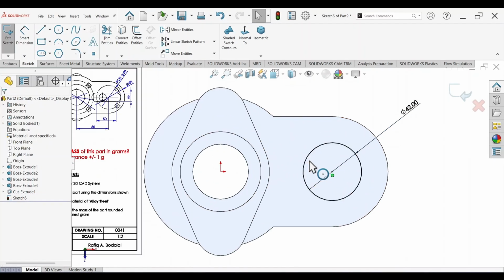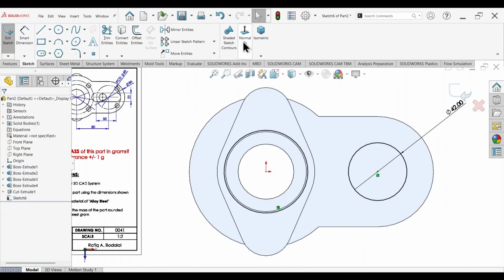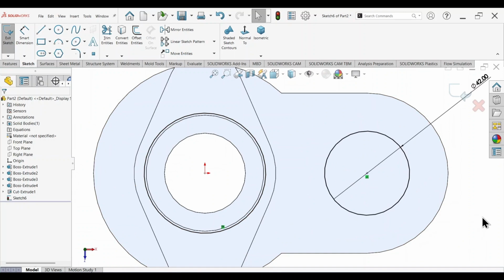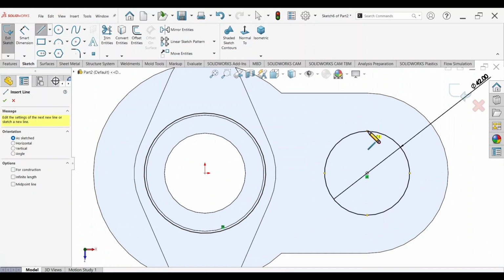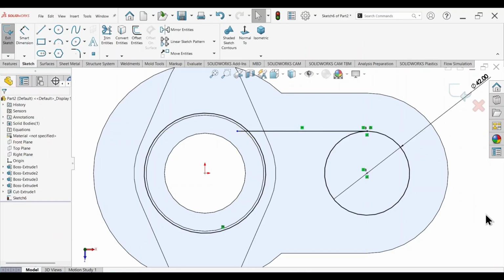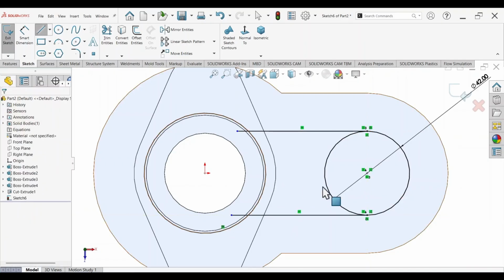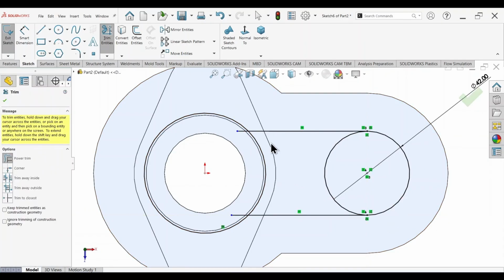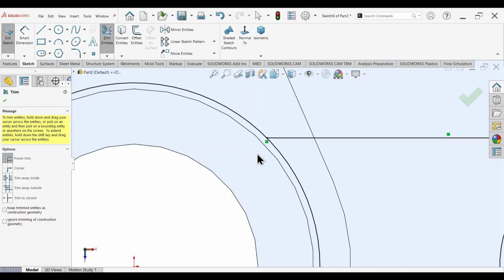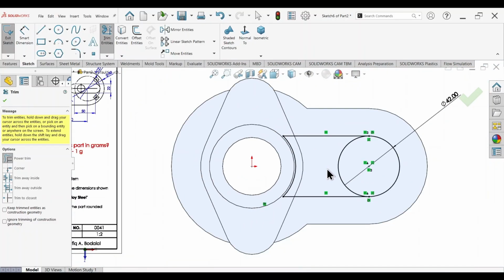And we need to close off this sketch with the bottom portion right here. So go ahead and select this edge, convert entities, normal, and what we need to do is activate the line tool, and starting from this point all the way, draw a horizontal line. Make sure the lines are horizontal. Activate the Trim Entities tool and delete any extra lines, leaving behind the basic 2D profile that we need. All right.